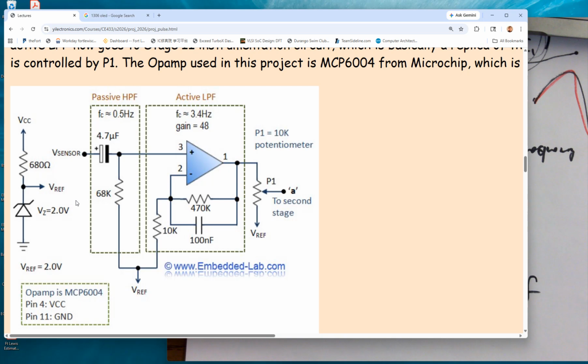That works. Use a voltage divider. Sure. Use an op amp. Yep. So what about the power supply for the op amps? You're probably curious, you want to open up the data sheet of the op amps and see what's the lowest voltage you can give to these op amps. You don't want to supply 5 volts anymore, even though it takes up to probably 6.4 volts. Usually people just use 5 volts, but we want to use the lowest possible.